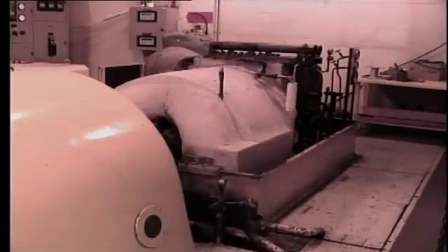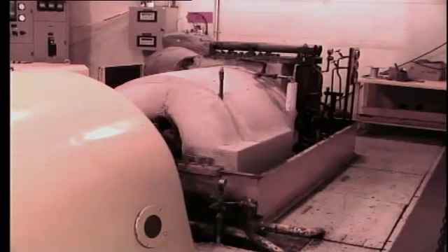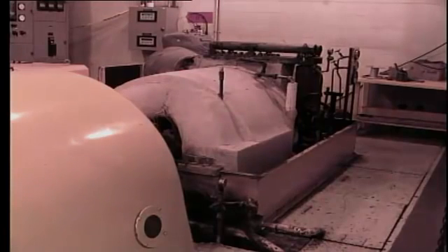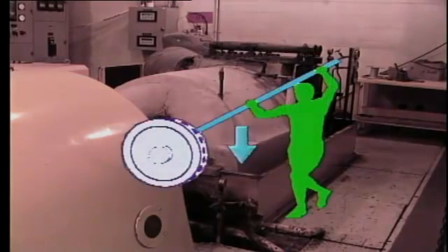One method adopted on smaller machines is to rotate the shaft by hand, if possible, say 180 degrees every half hour. On older machines, this was sometimes achieved by inserting a bar into the coupling. Thus, the first types of turning gear were often known as barring gear. On larger machines, this is not possible, and the only real solution for a failure of the turning gear is to admit steam once again to the turbine and run it up to speed.